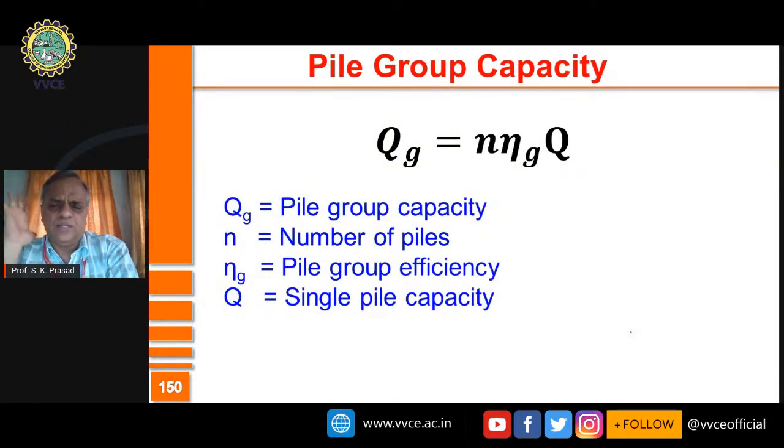So, well, friends, you are required to know that pile foundation does not involve only a single pile. A number of piles at the top are connected by a pile cap, a single pile cap. On top of the pile cap, the structure is built. So it is a group of piles which you consider in the design.